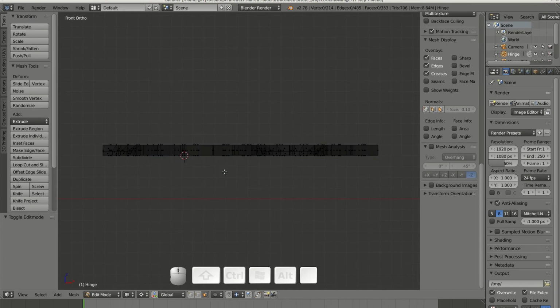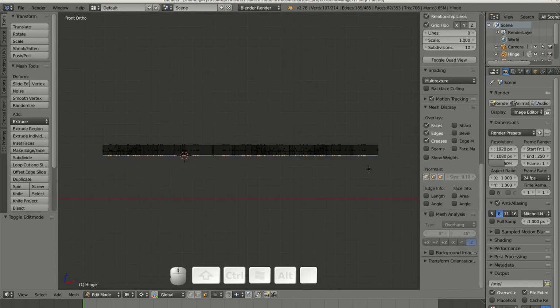The standard routine for creating regular mesh is to first extrude the edges parallel to the extrusion direction, then fill in the faces perpendicular to the extrusion direction, and then remove the doubles.